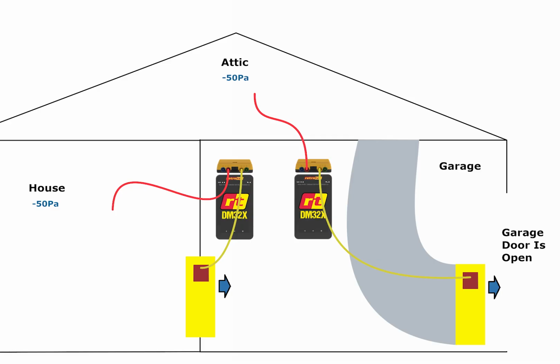When you have this scenario, where there's an attic access outside of the building enclosure, always use the duct leakage split kit. Don't use the plate. It's just a lot easier. The difference when you do this is that you're going to have your manometers outside, so it'll be easiest to place them in the garage. Then you'll have your red tubes on both manometers referencing back inside. On your primary blower door manometer, that red tube is just going to reference back inside the house.